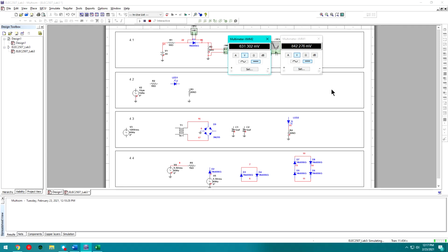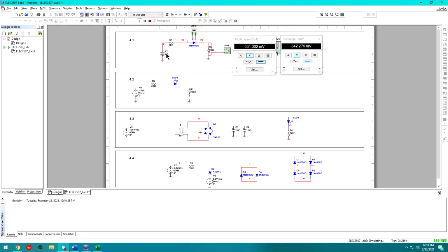And that means that the rest of the voltage in the circuit, so the rest of the 2 volts, has to drop across either the load or the source impedance. And because the load and the source impedance are so close in value, we actually lose about half the input voltage here, right? We're inputting 2 volts, and we can see that we're only getting out about, let's say, 1.4, 1.5 volts between the diode and the load. And that means the rest, another half a volt, is actually dropping here across the source. So let's go ahead and increase that there to 3 volts.